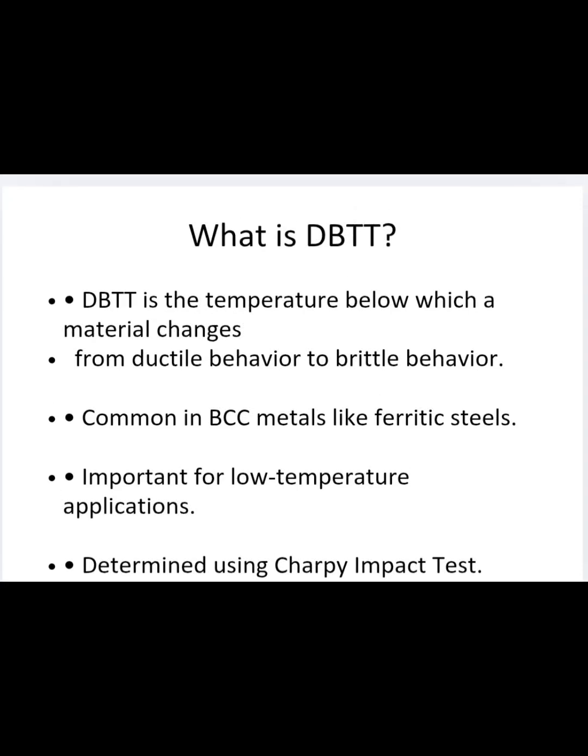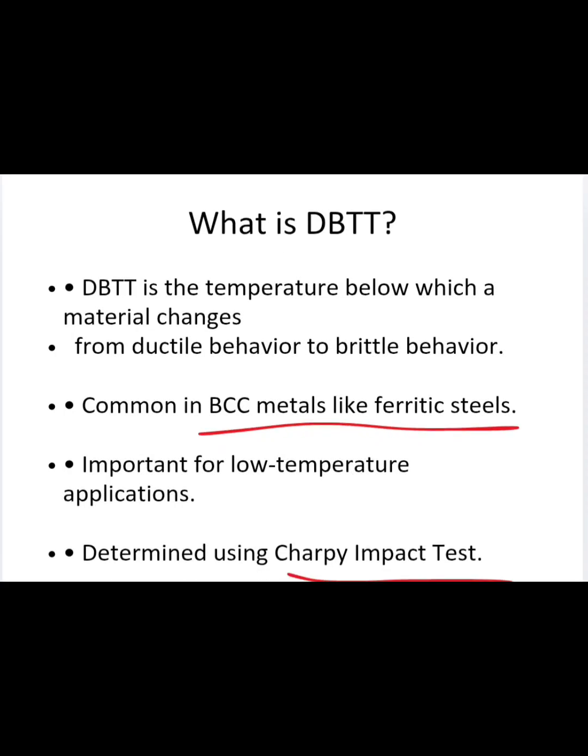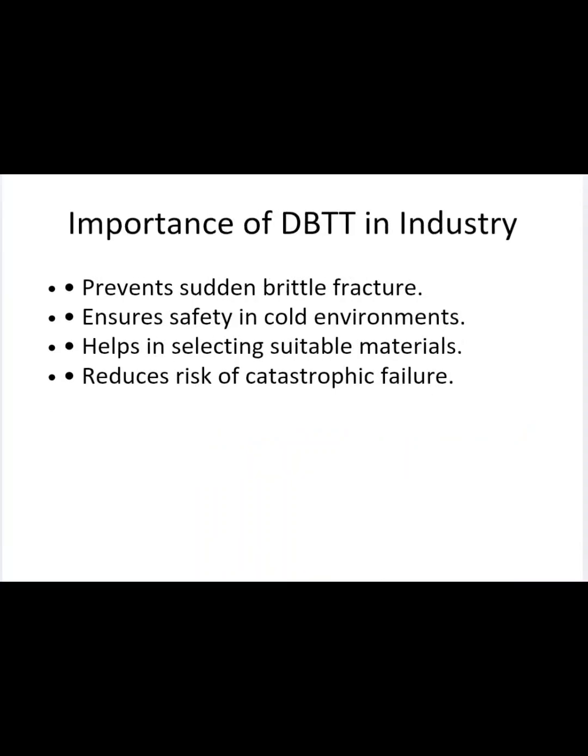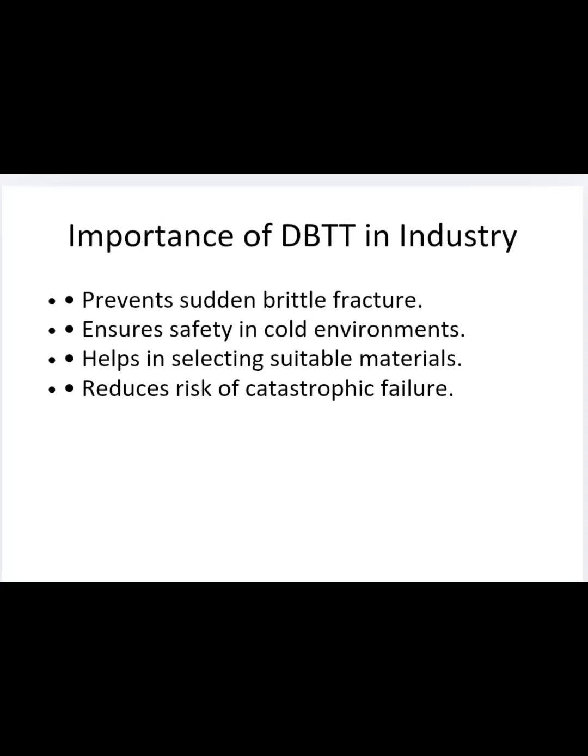The DBTT can usually be determined with the help of the Charpy impact test, and it is common in BCC metals like ferritic steels. Importance of DBTT in industry. The first one is that it can prevent sudden brittle fracture.